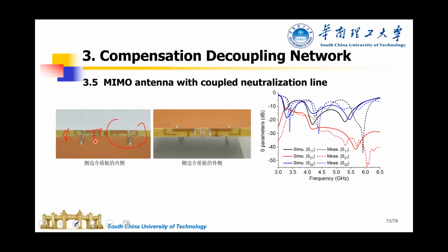But the conventional PIFA antenna is large and narrowband. So we use decoupling, because there is a gap where we can introduce capacitance. Capacitance can decrease the antenna length and also give wideband. This is the key of the design.